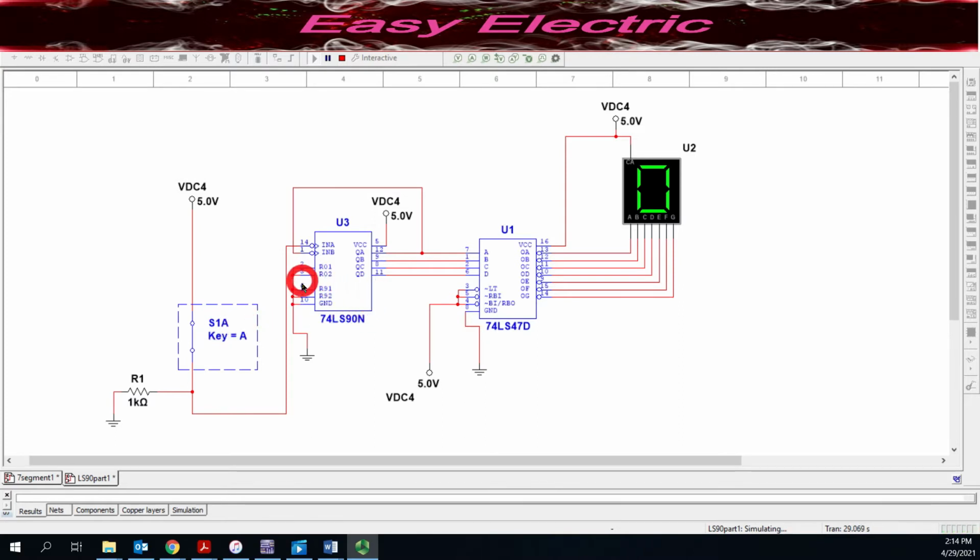We have a few pins here, 2, 3, 6, 7, 10, which we just deactivate with 0. Pins 12, 9, 8, 11 are the BCD output, and pin 5 is the VCC. We connect those to the input of the BCD to 7 segment converter so that we are able to see the result on our 7 segment. So let's start to do that.